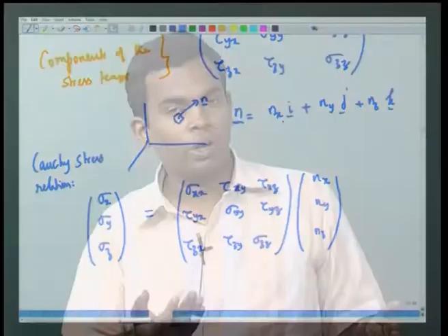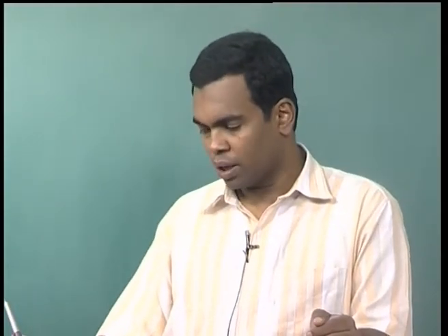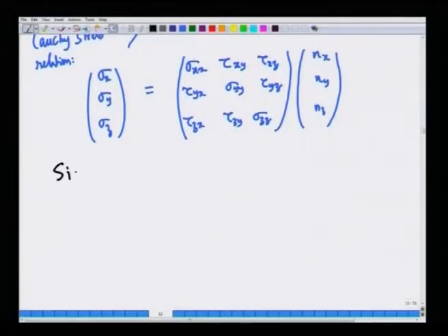Now, this is a very powerful result, because in principle you might have imagined that to find the stress at a point, since you have to specify also the orientation of the surface, you have infinitely many orientations. You may imagine that you have to tell a whole lot of information, because you have to keep on changing the orientation to find the stress. But the Cauchy relation tells us that it is not necessary to keep on measuring or calculating at an infinitely large number of orientations. All you have to do is to measure the force per unit area along the 3 coordinate directions, and once you have it, you can find the force that acts per unit area on a surface with any arbitrary orientation about that point. This is the power of the Cauchy stress principle. Now, whenever we define things like stress or work, there is always a sign convention. So, we have to be a little clear about the sign convention.